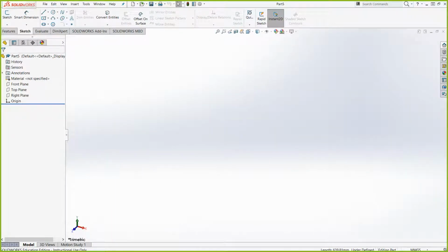So for the loft to work, we're going to be using some planes. So maybe before I do the actual loft, let me show you how to add new reference planes. Because for the loft to work, you're going to have to offset planes. This way you'll be able to build it. So let me actually show you first what specifies a new reference plane. I'll talk about the 3-point, the lines, and a couple other plane options.